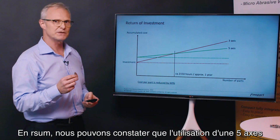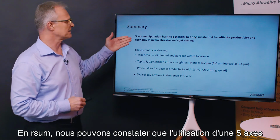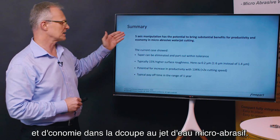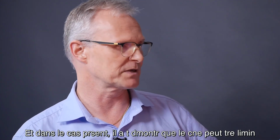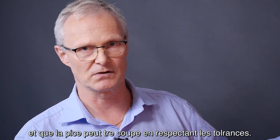To sum this up, we can see that the 5-axis manipulation has the potential to bring substantial benefits for productivity and economy in microabrasive water-jet cutting. In this current case, it has shown that taper can be eliminated and the part can be cut within tolerance.